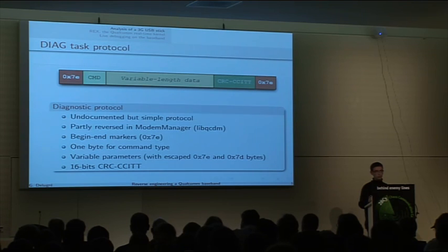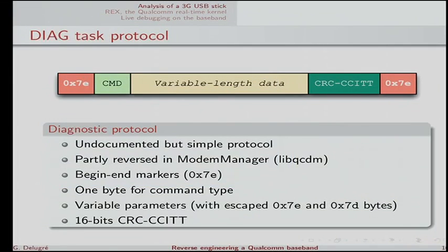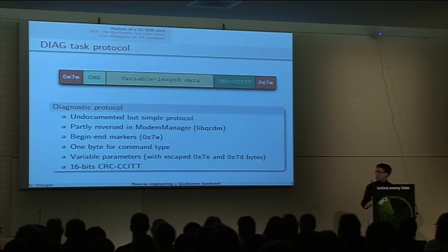protocol, and the protocol is fairly simple. It's not documented, obviously, because it's an engineering protocol from Qualcomm. It has been partly reversed in ModemManager. If you look into the source, there is a directory named libqcdm, where you can find part of the protocol. So you have begin and end markers, 1 byte indicating what the command is, variable parameters depending on the command, and a CRC.